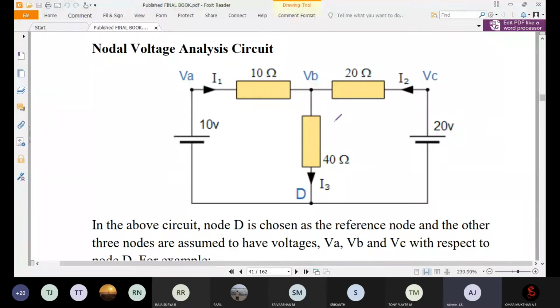Okay, so now we will see the nodal analysis. Nodal in the sense we are going to make a node. You know what is a node? Joining of some terminals. There are 1, 2, 3 dots available, right? I will mark them. These are called nodes, where many connections are connected together. And this one is always called the ground mark. The bottom, where the negative terminals are connected, always becomes the ground. So this voltage is exactly equal to 0 volt.